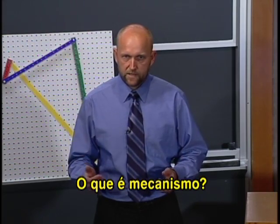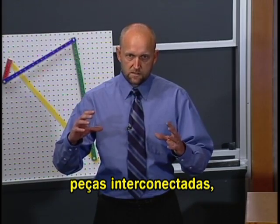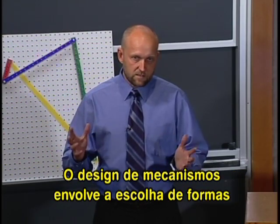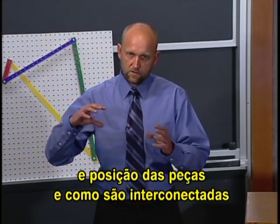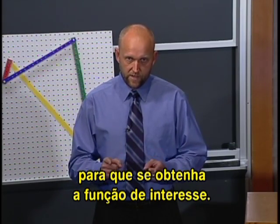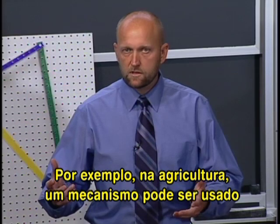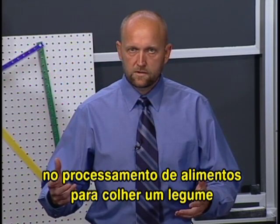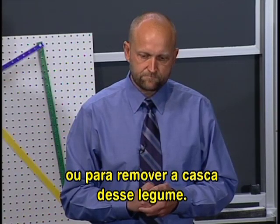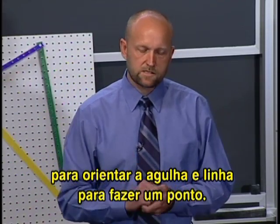So that's design. Now, what's a mechanism? A mechanism is a collection of items, parts, that are interconnected so that their motions are coordinated. So design of mechanisms involves choosing the shapes and locations of those parts and the way they're interconnected so that you get the function that you're interested in creating. Now, mechanisms are all around us. For example, in agriculture, a mechanism might be used in crop processing to pick a vegetable or to take the husk off of that same vegetable. Also, a mechanism might be used in a sewing machine to guide a needle and thread and make a stitch.